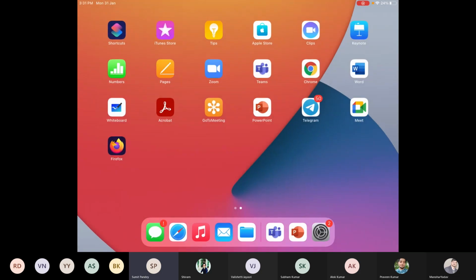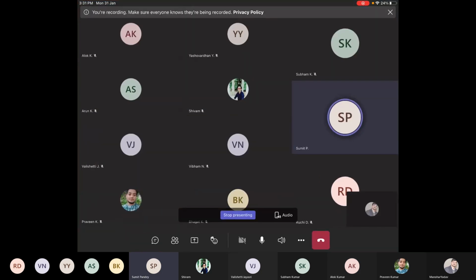No, sir, because the NIR band lies from 0.7 to 1.3 micrometer. That is correct. 0.7 to 1.3 micrometer is the NIR band. So do we get enough reflectance from water in the NIR band, if you see the spectral signature of water? No, sir.